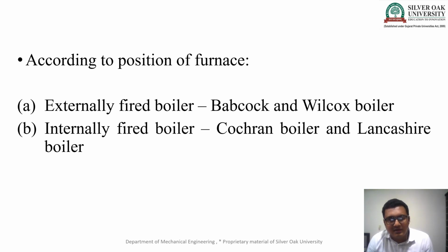And what is an internally fired boiler? The furnace itself is inside the boiler. What is the function of the furnace? In the furnace we burn the fuel, solid, liquid or gas. After the fuel is burnt, heat energy is generated, and that heat energy, or hot flue gases, is transferred to the water, and the water gets converted into steam. As examples, the Babcock-Wilcox boiler is an externally fired boiler. Cochran boiler and Lancashire boiler are internally fired boilers.